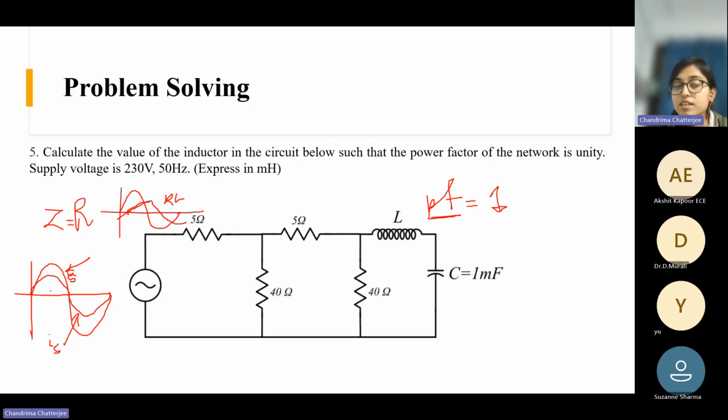So now in this case the power factor is 1 because the voltage and current are in phase. But here the power factor will not be 1, it will be less than 1 because now they are not in phase. The current is lagging the voltage. And for RC circuit it is the opposite. Now the current will lead the voltage. The current zero crossing will happen earlier than the voltage zero crossing. Okay, so that is the case for RC type of load.